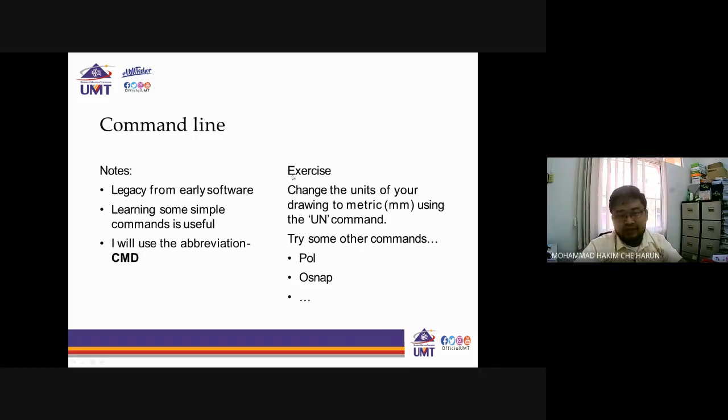So this is one of the exercises that we made before. The exercise was to change the drawing unit to the metric form in millimeters. As I've mentioned before, the default setting for AutoCAD is usually in foot, where people drawing their house plan and architecture usually use foot and feet, or the American unit. So I would recommend using the metric millimeter by using the units command, where you can simply type unit in your AutoCAD.